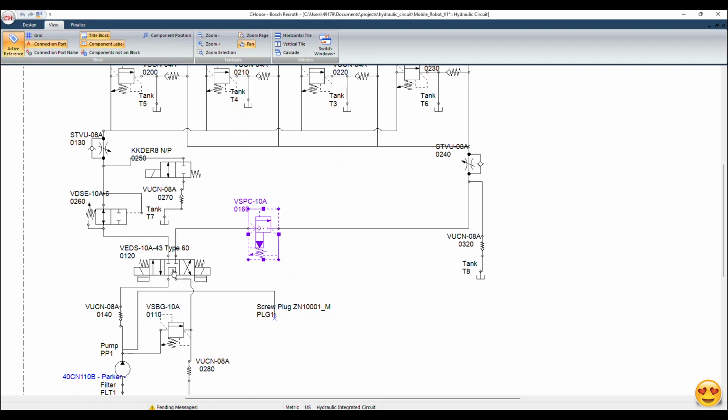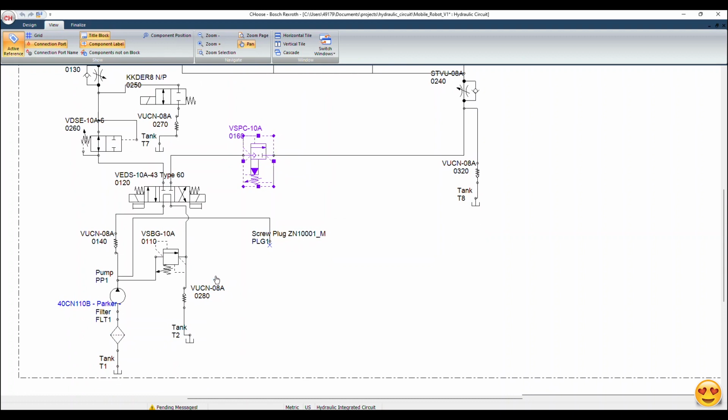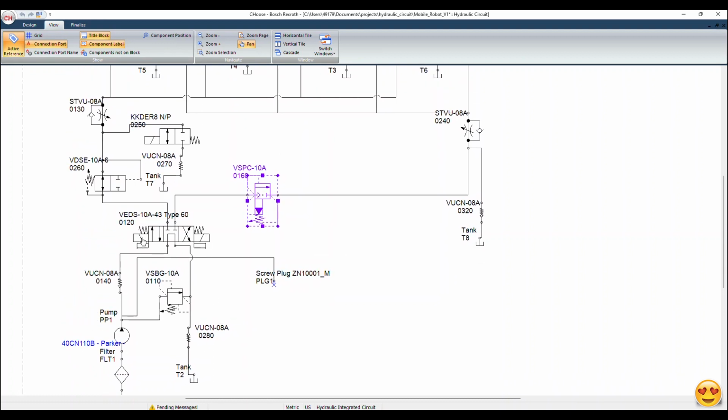There's actually a spool inside a cylinder, with some holes, or let's say a manifold, that the fluid can go through. So it depends on the position of this spool. If the spool is in the middle, it means it is in a neutral position. So whenever the flow comes and gets to the valve, because the valve is in neutral position, it goes back to the tank.